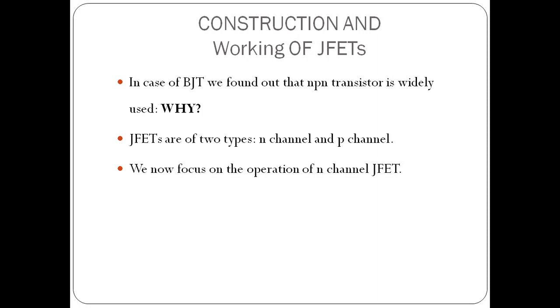In case of PNP transistor, the majority charge carriers are holes. We know the holes have more effective mass compared to the electrons. Therefore, electrons have high mobility compared to the holes. This is the reason why NPN transistors or NPN bipolar junction transistors are widely used.